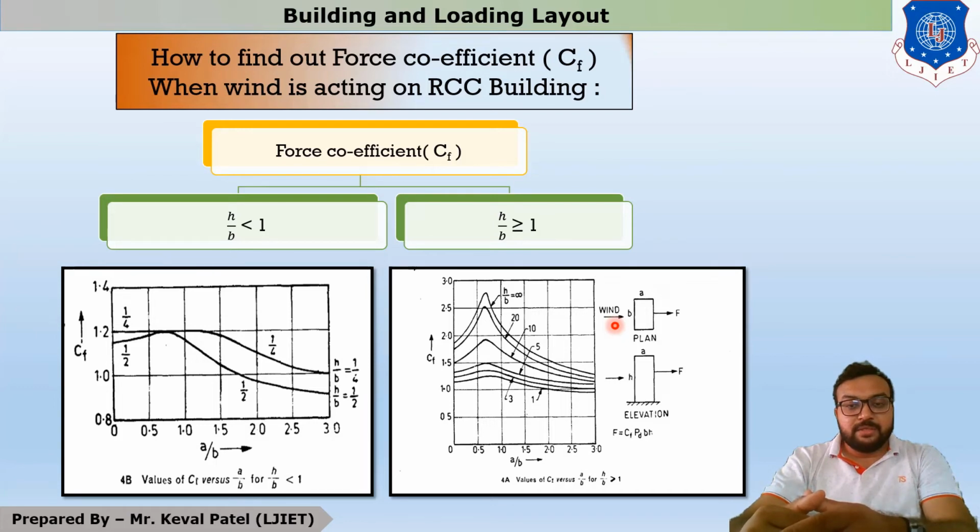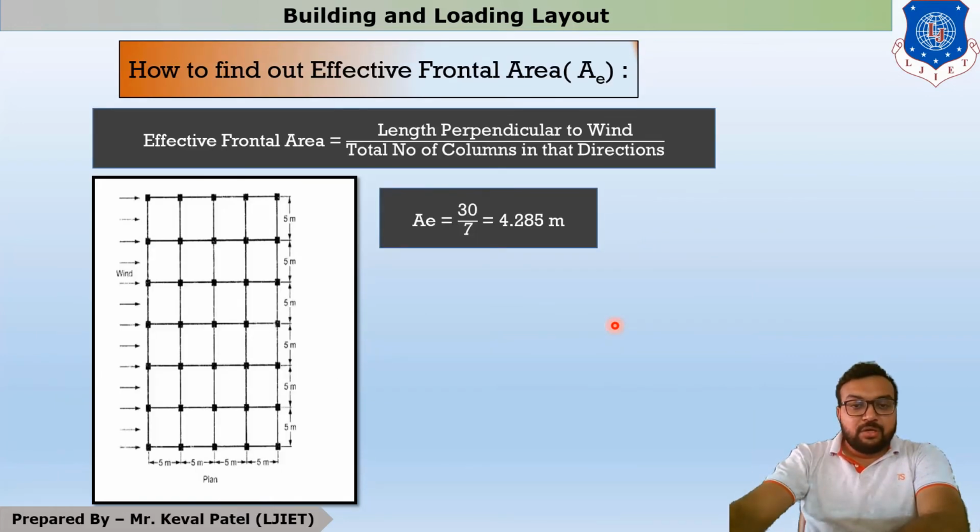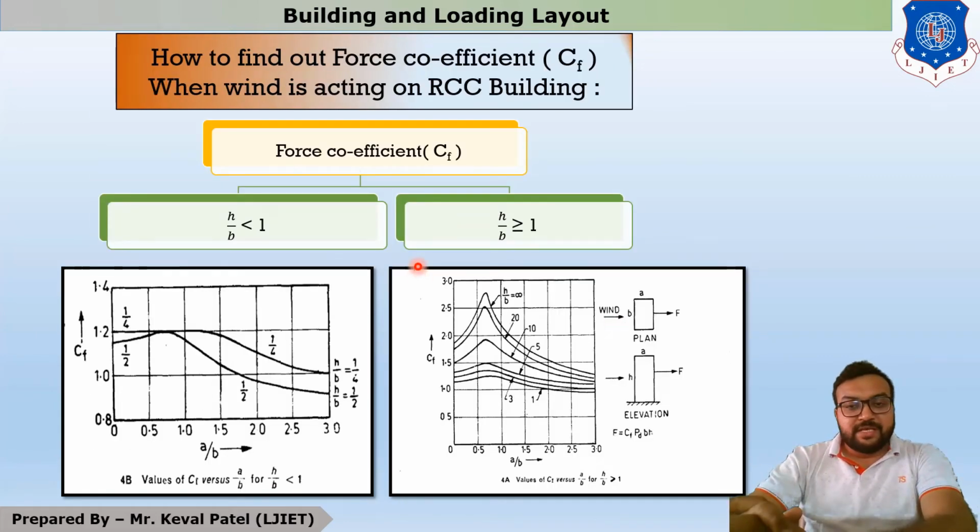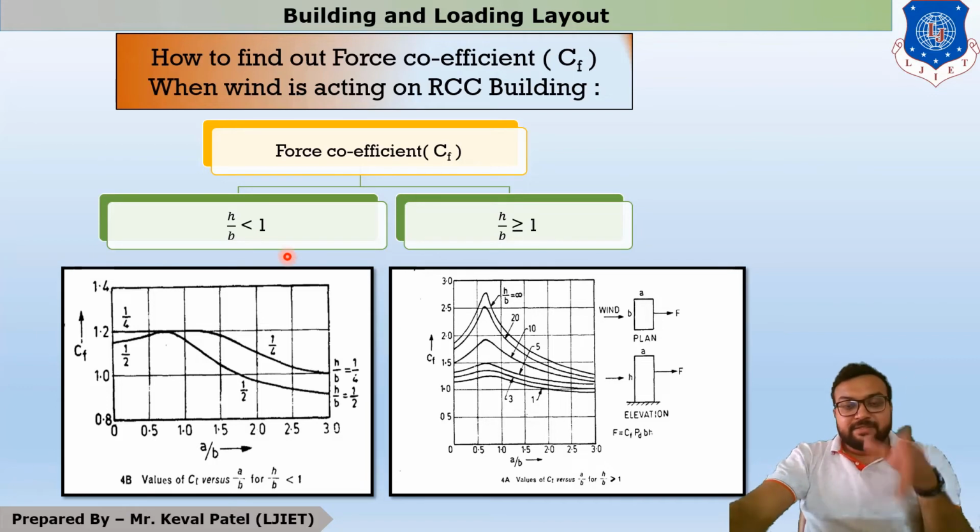Now the term is to find out CF when the wind load is acting on any water tank. Okay, so whenever a wind load is acting on any water tank, then you are referring page number 40. So all the students move to page number 40, in which our y axis is written as CF upon 1 plus 2 epsilon by D and x axis is written as RE.